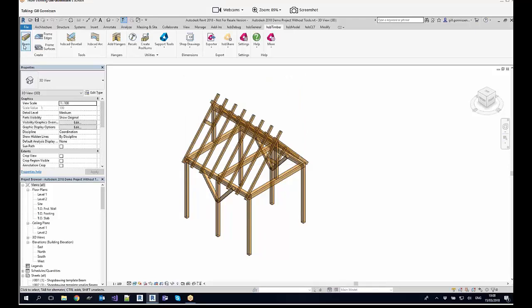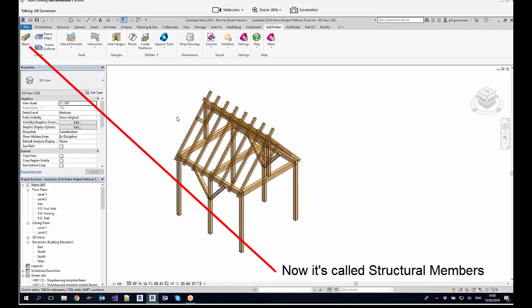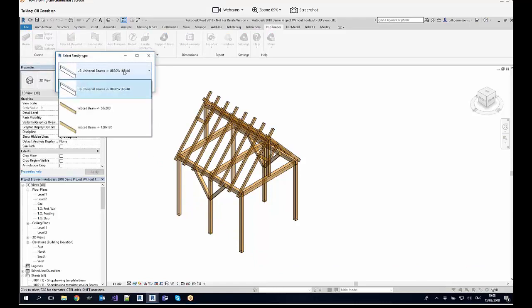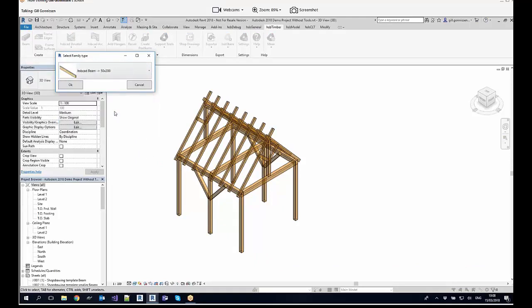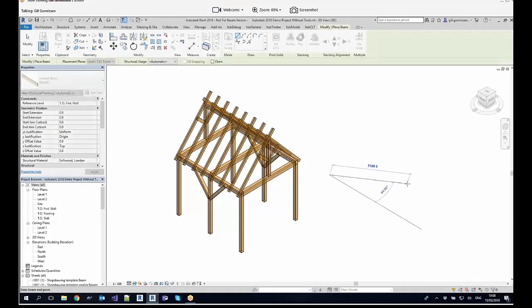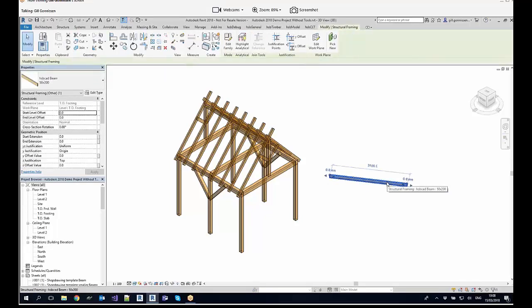Then I'm going over to the start of the ribbon. We can create some beams and insert some beams that are really hsbCAD beams. So here we can select the family types that are really Revit types, and then we can just insert the beams that we need. As you can see, these are hsbCAD beams, but they are Revit families.